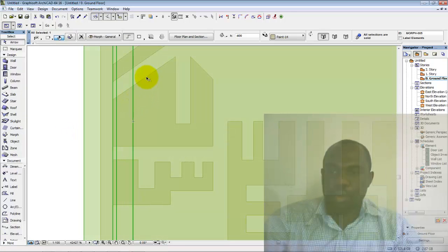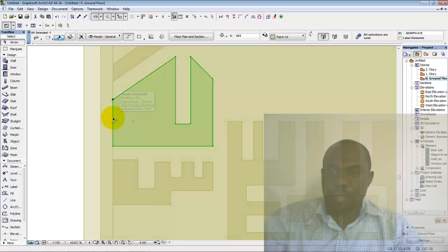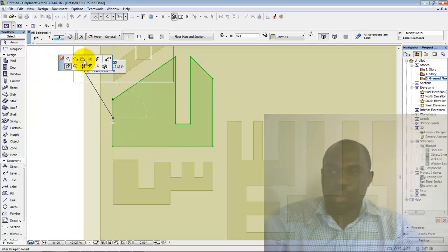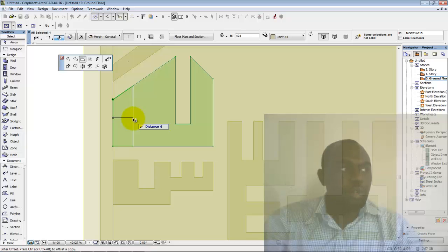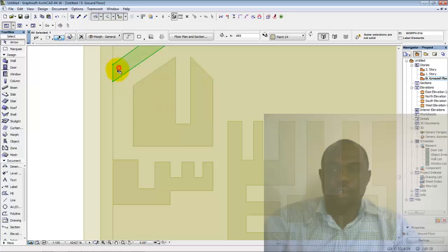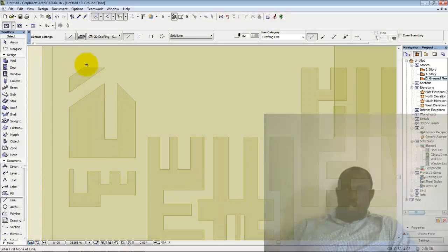We'll come here, select the shape, and use offset edge, so you can determine where it's going to end by when the cursor changes to the perpendicular side. That gives us this. Having done that, we've adjusted these shapes to follow this line.